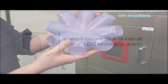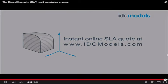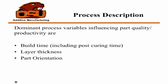They haven't actually mentioned anything about what machine they're using. So I've changed a few things as to what comes over here. Build time is an important characteristic, but it's more of a dependent variable based on layer thickness and all that. So the two things I added instead of build time were post curing as a separate factor, and also overcure.